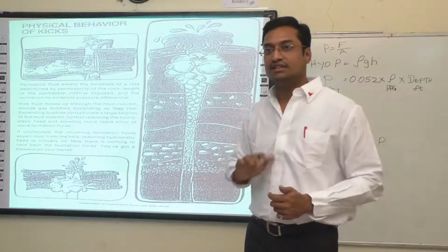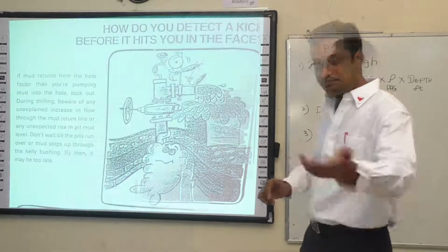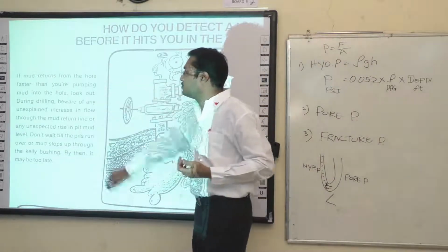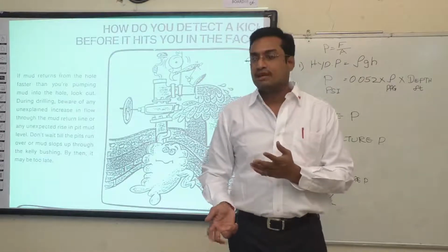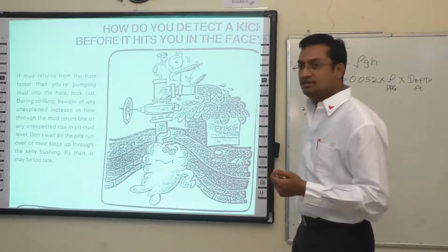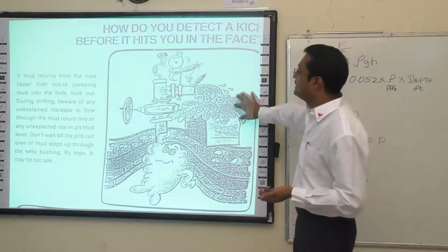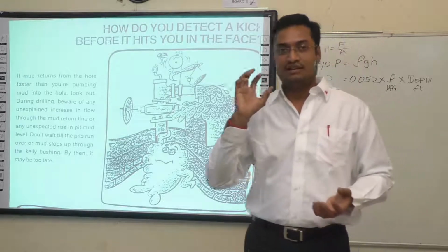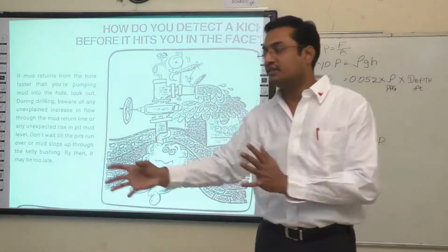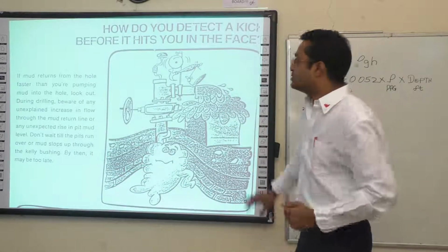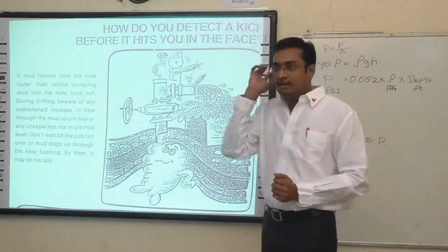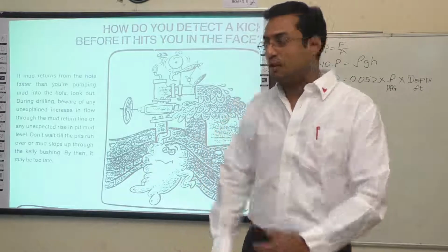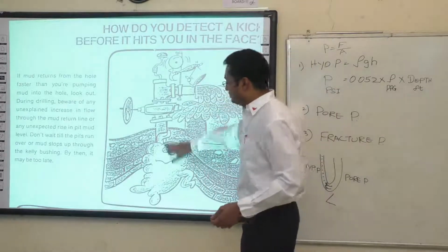That is well done. So, if mud returns from the hole faster than you are pumping into the hole, that is an indication. It means how you detect the kick. How you identify that a kick situation has happened. You are pumping 250 gallons per minute inside the wellbore while drilling.